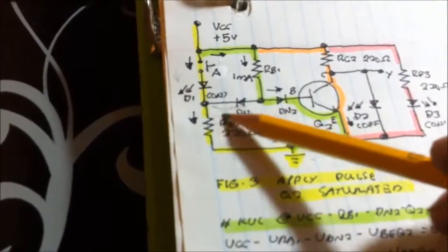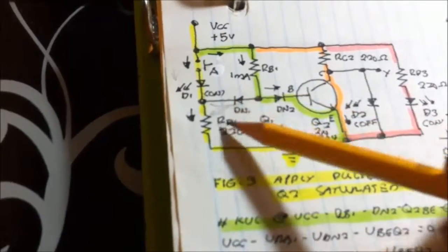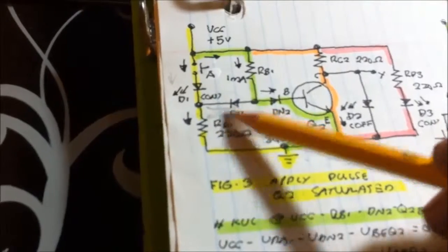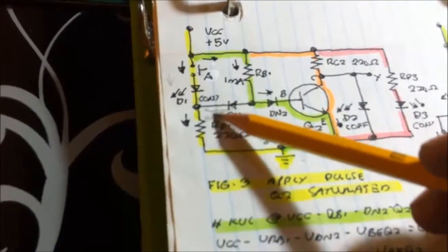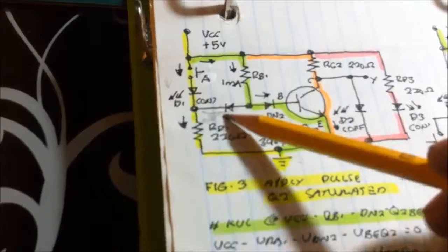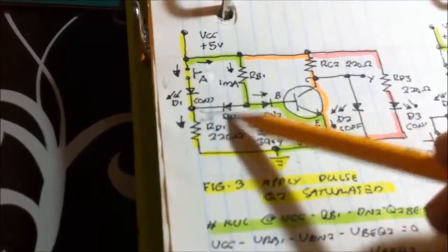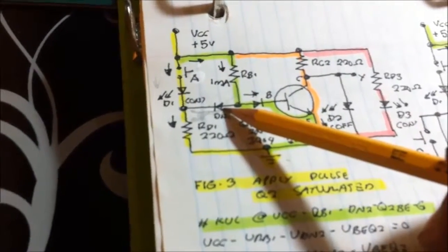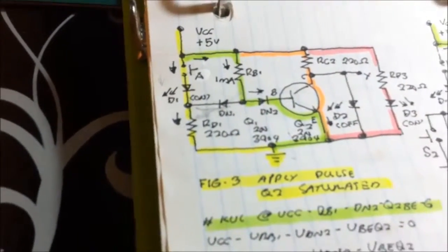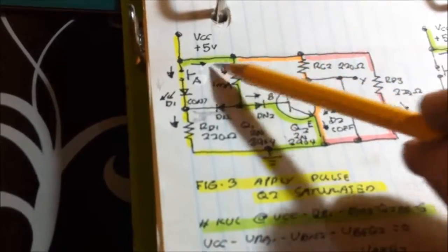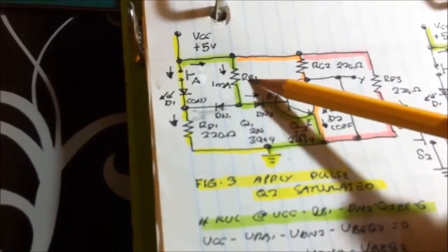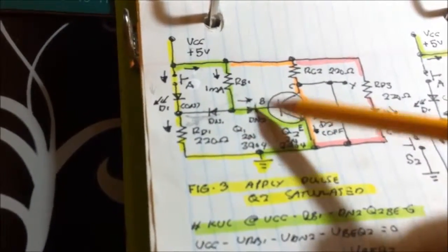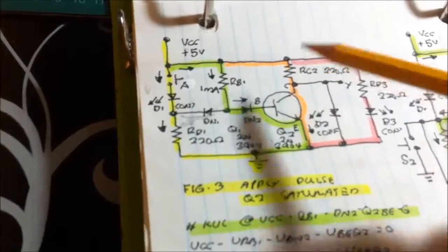Since this is the input side, sending a high level or high voltage here, or logic 1, makes this transistor reverse biased. Since this is reverse bias, the current flows now from VCC to the base resistor, to the base-collector junction of the transistor.